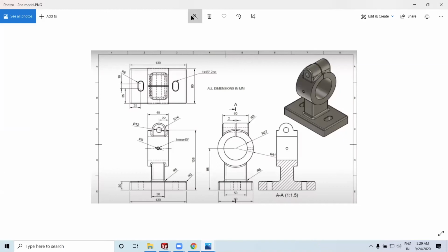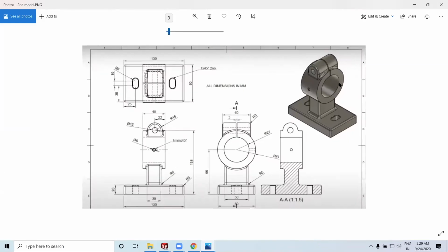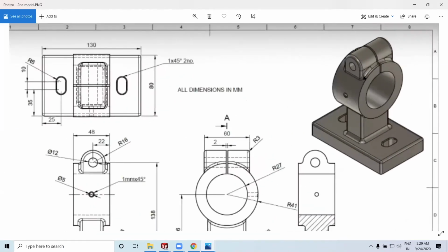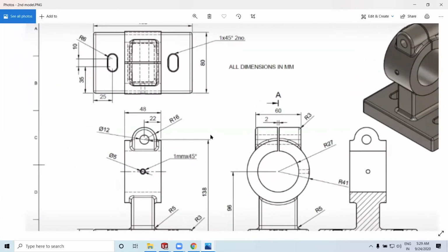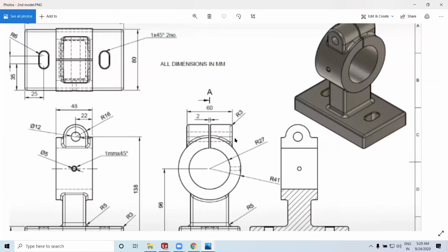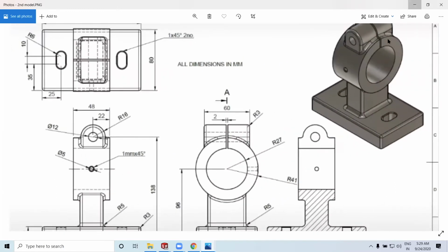Just that if you see, there are these circular sides which have been added using the fillet feature to get rid of the sharp edges. So we do that. We implement a radius of 3 units for the fillet.